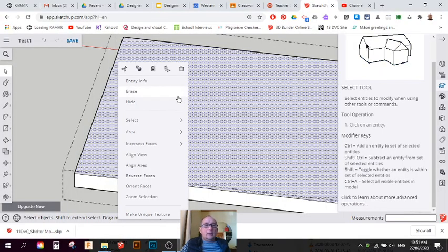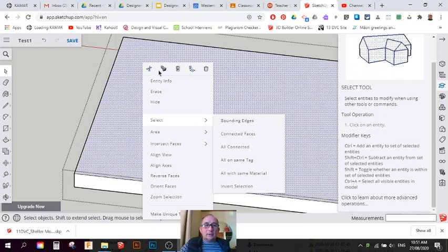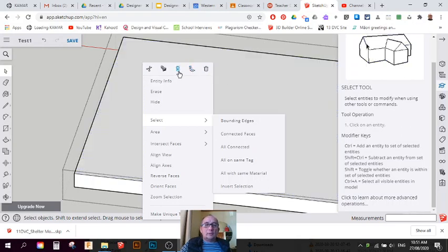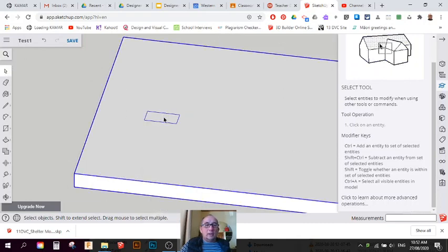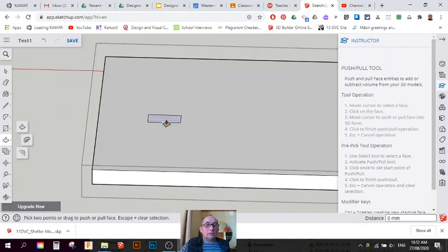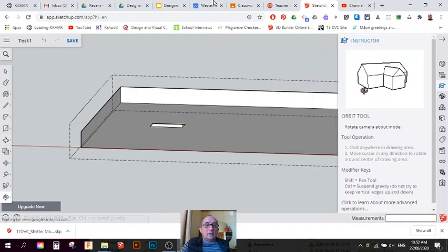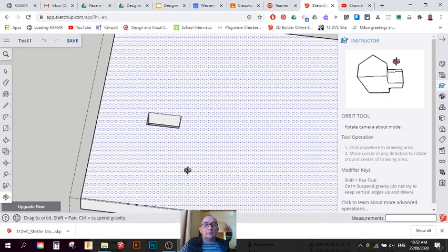Okay, so I'm back. Found it. Right, so right click, and then here we can choose either paste, which is this one here, or paste in place. Right, so when I do paste in place, it will create my object back where I originally had it. And so it's now inside of the component, right? Which means we can now push it through as a whole. Snap it to this corner here, and now we've got a nice hole sticking through.